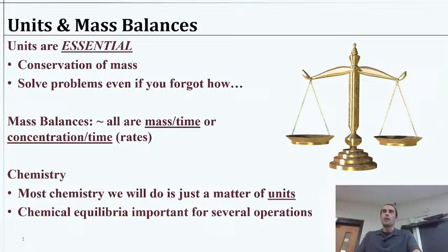So I mentioned this is all about conservation of mass. So that's essential. And as we move forward, we're going to talk about what we call a mass balance. And what we're referring to there is some accumulation of mass into a system over time. Sometimes we will have a net zero accumulation, but we can still set up the mass balance to understand the conservation of mass. We'll have a problem in a little bit on that. If you think about a stream that runs into a pond, and there's a stream that's exiting, we could call the flow rate of that stream Q